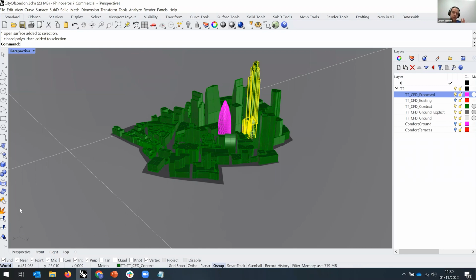For the outlet, it actually needs more than that. It needs to be longer. So you want to have 10 to 12 times that height. On a building this size, so this is about 300 meters, that inlet plane is in the range of a kilometer and a half, if you really want to do a full res simulation. And the outlet is almost 3 kilometers behind the building. But then that rotates around, right? And the tunnel has a width.